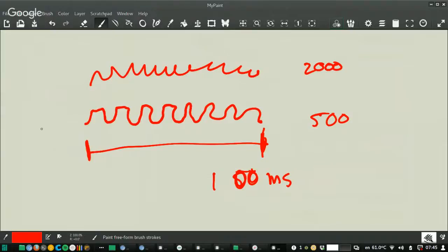It's not actually measuring this rise time, but setting a fixed time like 100 milliseconds or whatever, and counting how many times I'm charging and discharging this. This is the approach they are using. I think it's a more clever approach than the one that Neil is using, because this is more precise.